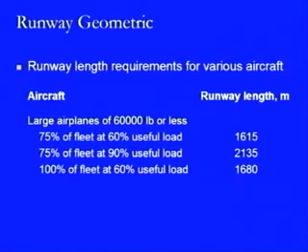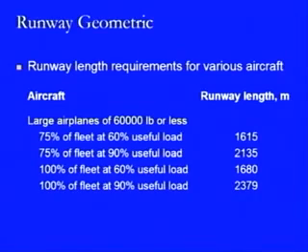So, there is a small change in the length of the runway strip with respect to the size of the fleet, whereas if there is a change in the useful load, then there is a big effect. That is what is coming out from this information or the data which is being presented right now. In case we have 100% of the fleet, but the useful load has been increased to 90%, then what we found is that there is a big increase in the length of the runway strip, and it is 2379 meters.